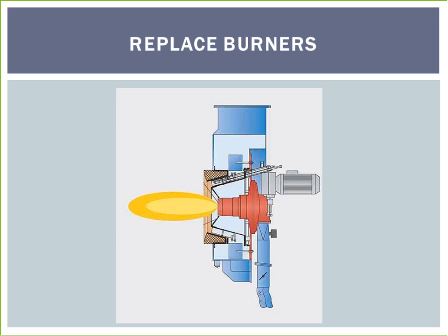If you presently have an old, inefficient oil burner, such as rotary cup or atmospheric, or an oversized burner causing excessive short cycling, it may be cost effective to replace the burner with a modern, efficient, and properly sized burner. You may want to consider variable firing rates and/or dual fuel capabilities, allowing you to choose the least expensive heating fuel at any given time. Natural gas burners can replace oil burners without requiring boiler replacement.